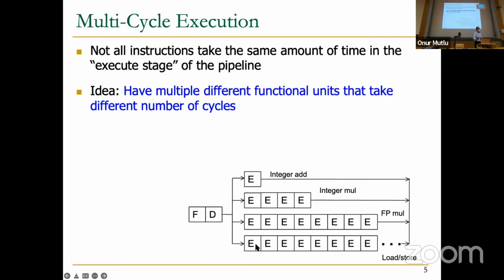And if you look at this, then you have a problem with this picture. Because you fetch and decode instructions in order, send them into the execution units in order, and one instruction takes, let's say, 60 cycles to complete. Another instruction that comes after it takes 1 cycle to complete. So what do you do in the write-back stage, basically? These execution units can be pipelined or not pipelined. It's not as important. The important thing is they take 60 cycles. Pipelining, of course, is better for throughput.